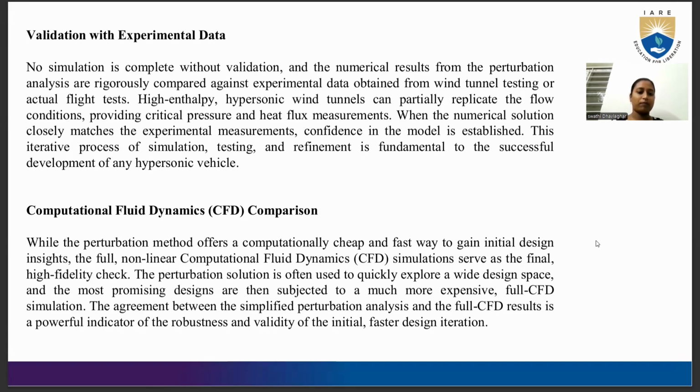Computational fluid dynamics, CFD. While perturbation methods offer a computationally cheap and fast way to gain initial design insight, the full non-linear computational fluid dynamics simulation serves as the final high fidelity check. The perturbation solution is often used to explore a wide design space, and the most promising design is then subjected to the much more expensive full CFD simulation. The agreement between a simplified perturbation analysis and the full CFD result is a powerful indicator of the robustness and validity of the initial faster design.